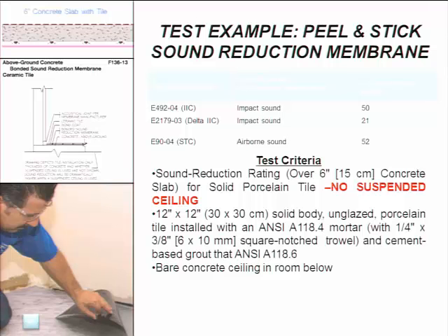Was it put down, per se, with this one with the primer, and did they use a regular mortar over the top of it, or did they use a mud bed? It is important to look at that test report, and within the test report it is well defined the system that was built and tested, and you're going to want to look at that to make sure that what you're comparing is what you're looking to achieve.